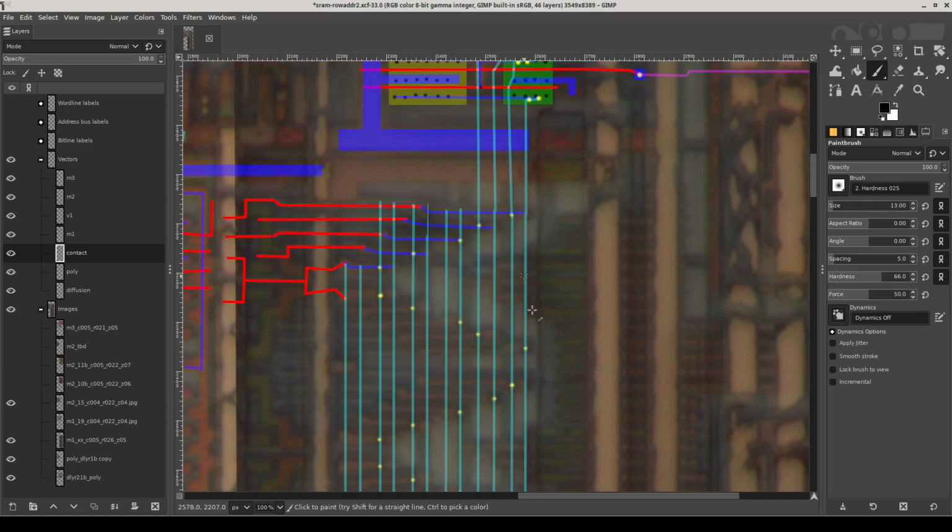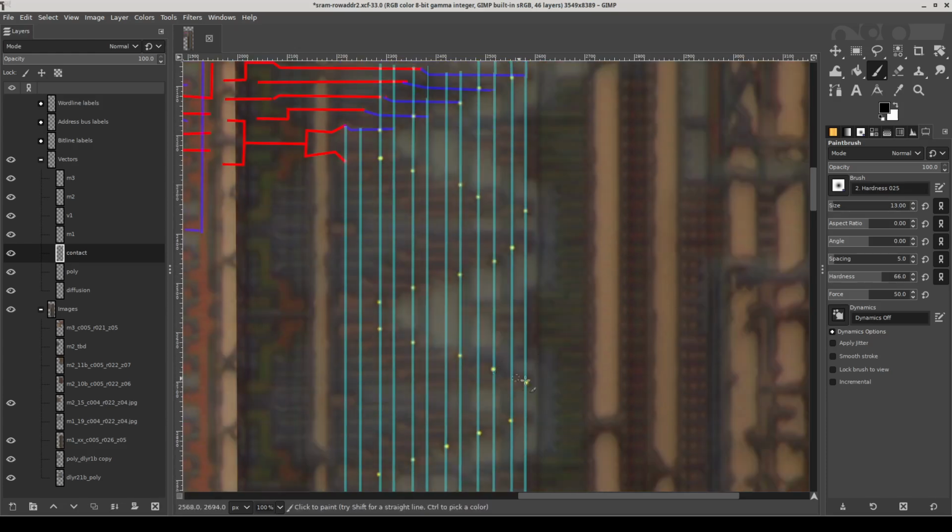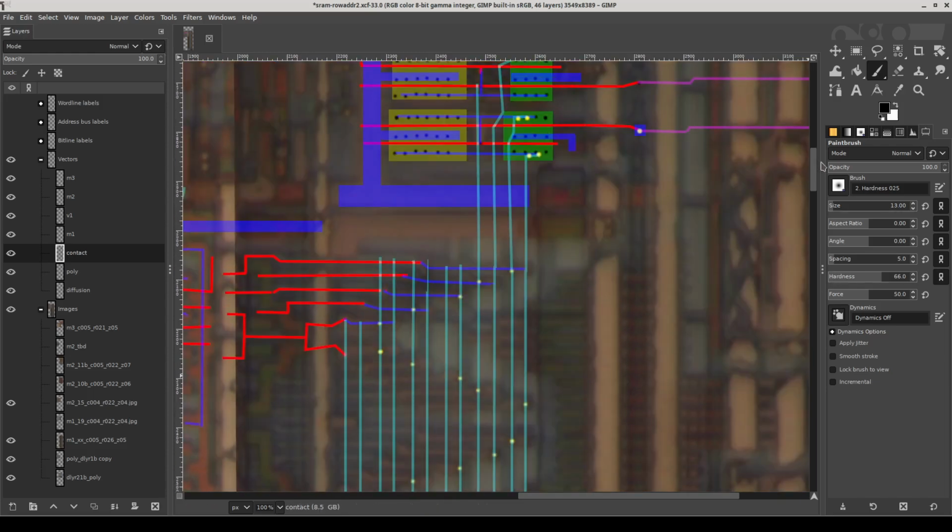So we've got left, left, left, right. Right, left, right, right. That sound familiar? And so it looks like we essentially have a binary counter with each bit encoded by 2 lines, and exactly 1 of these is going to be brought high at a time.